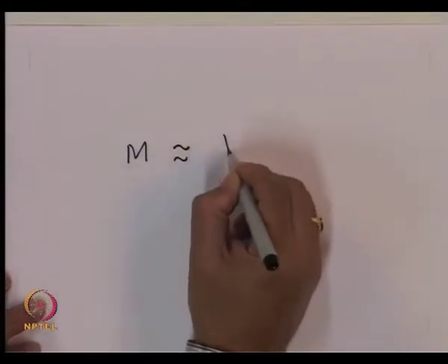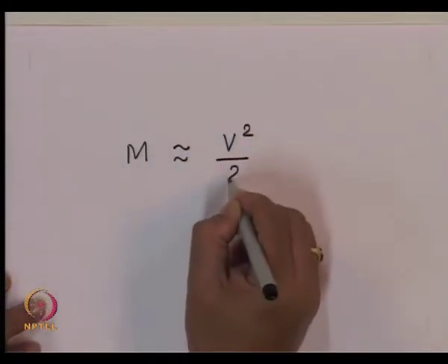Like that, if we consider the degeneracy for all the modes which are going to propagate for a large number, one can then sum up the total number of modes which are going to be present in each of these groups, and then one gets a result which gives us the total number of modes which are going to propagate inside the optical fiber, and that is approximately given by V square by 2. So, the total number of modes M is approximately equal to V square by 2.